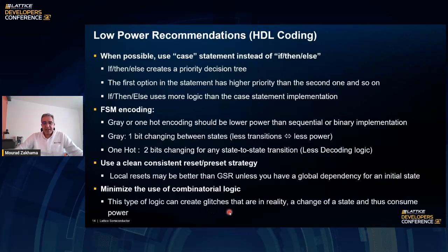So if you have an AND gate with one pin coming from the external world and another coming from internal FPGA logic, a noise glitch on that external pin, or a difference in the time these two signals change, will create a glitch, and that's also a transition.